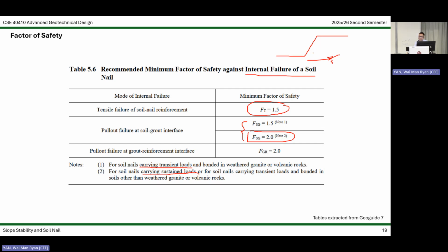But based on the calculation from a numbers perspective, the FOS is not sufficient. Maybe I need to design up to 1.4, and now the current slip plane failure surface is maybe just 1.1. Not good enough. I design soil nails to reinforce it.